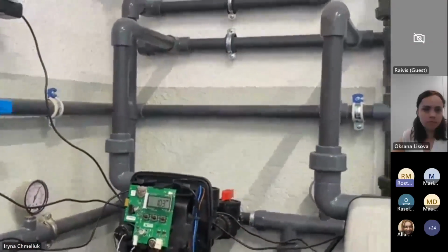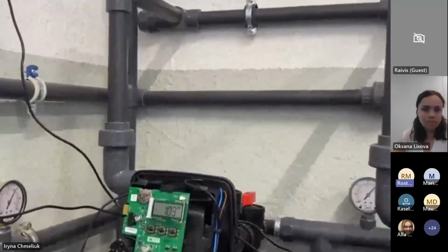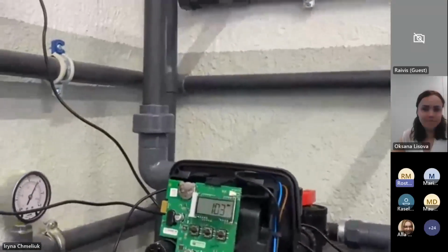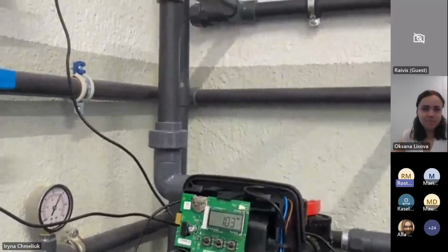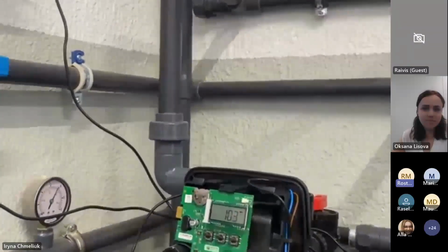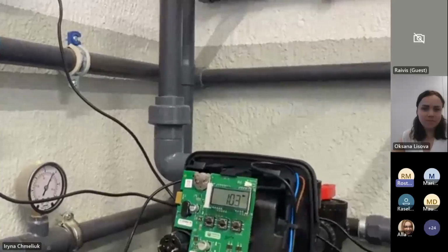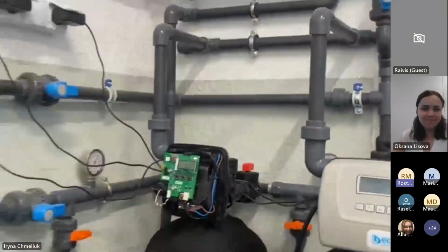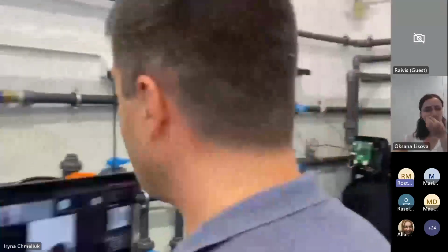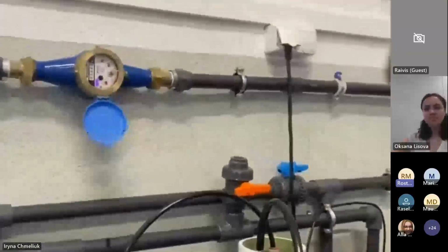Actually, it is here. So this is the way it is connected. You just screw it here, and then you connect the first and the third contacts on the microswitch, and then you lead it. I will show it, because it is open. And then you have to